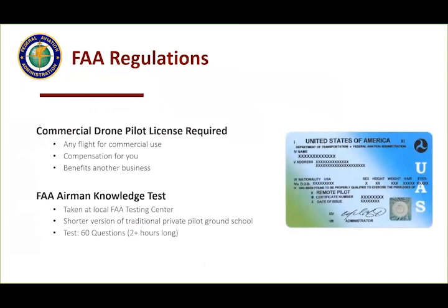Yeah, what you're going to want to do is familiarize yourself with FAA Part 107, and one of the questions I always get from my students is, do I really need to get a commercial license? The commercial license is based on any compensation for you or the benefits of another business. And generally, I would tell people, if you're getting paid to fly, get the license.